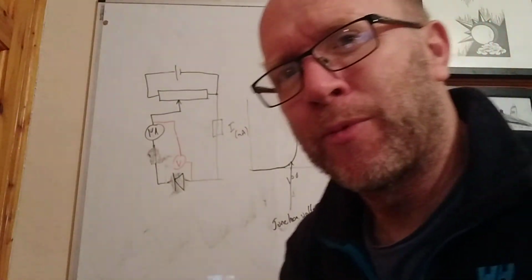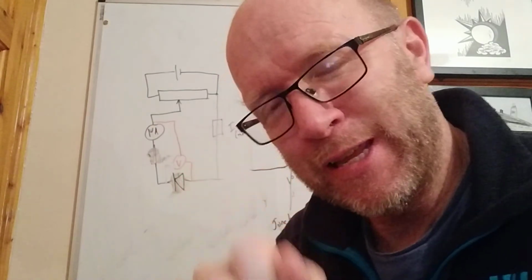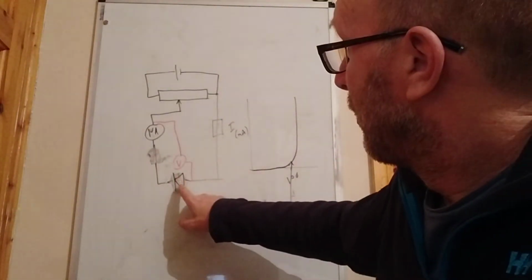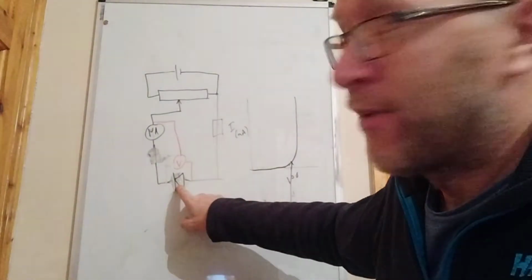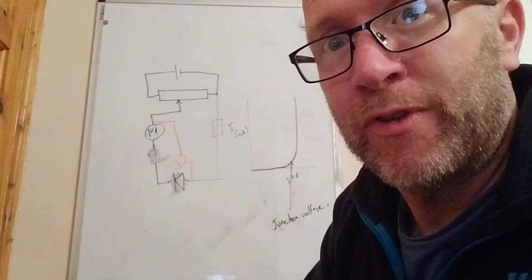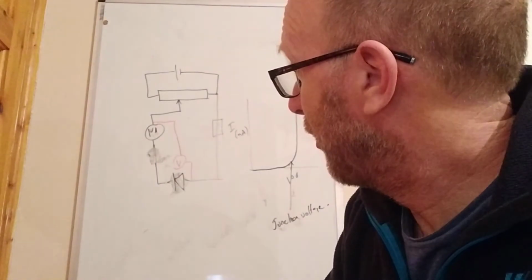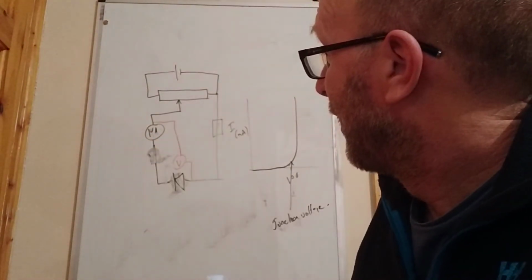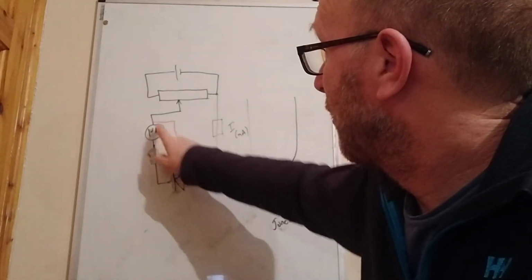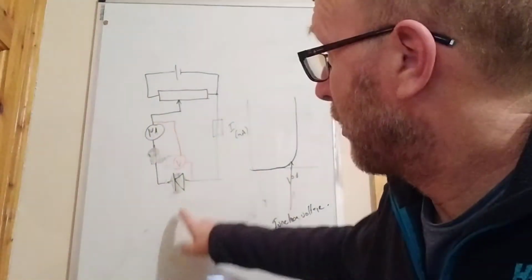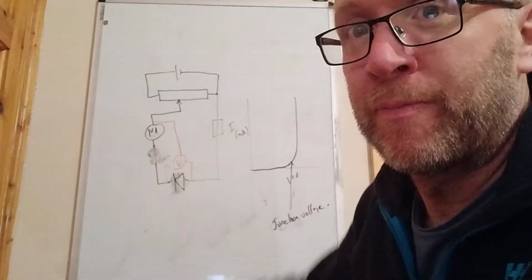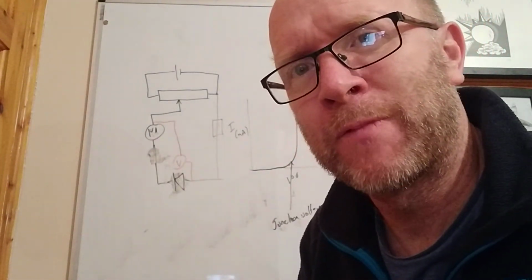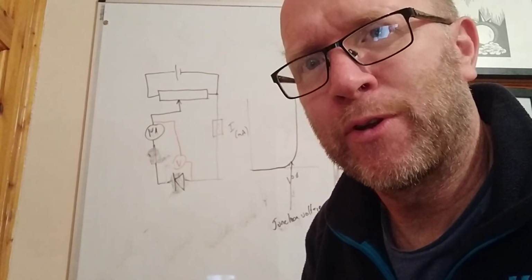Okay, so the voltage, remember, is the energy needed to drag the charges through the diode. Now, the diode has a huge resistance. A microammeter has a tiny resistance. Ammeters have small resistance. So therefore, because this is a huge resistance and this is a small resistance, the energy needed to go from here to here is effectively all used in going through the diode, or almost all used. So that's a much better approximation than doing it the other way.